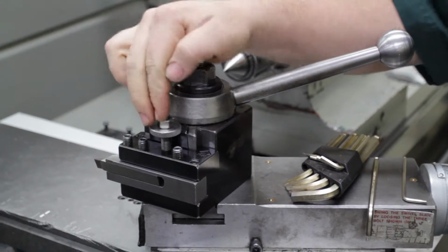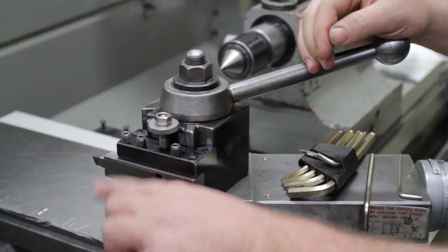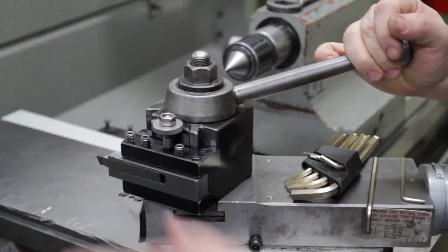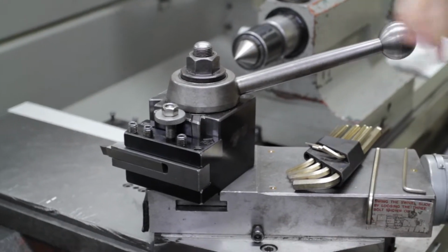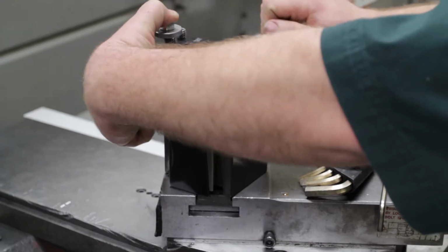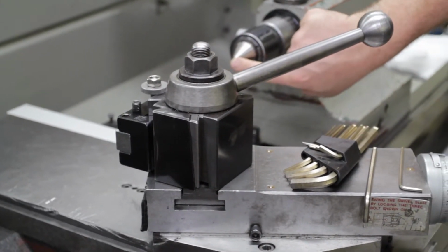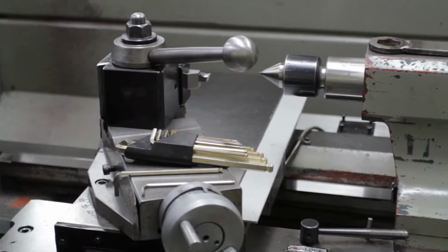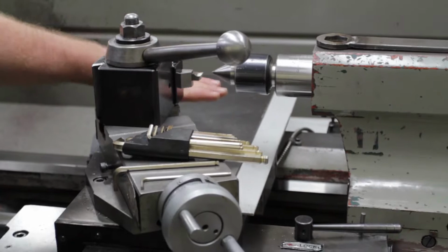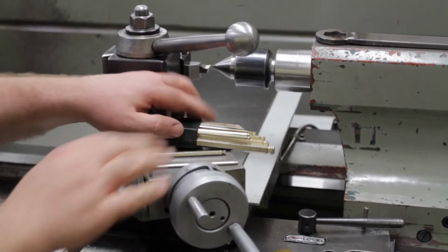So after you get this in there, you have to check the elevation of your tool. How tall is that tool? Is it on center with the machine? And we're talking about the center line in that direction. There's two ways to check that. One way, you could put this on this side, and then you compare it to the tailstock. As I bring the tool bit closer to the tail center, I can compare it to its vertical height. And that will get you close.